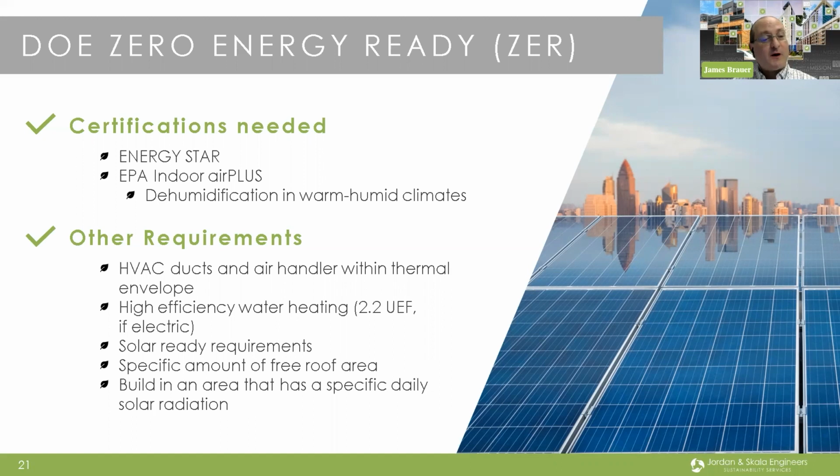Some of the other requirements outside of certifications is it does ask for you to have your HVAC ducts and air handler all within your thermal envelope. We touched upon earlier that have a high efficiency water heating system, which if electric, that does mean a 2.2 uniform energy factor, which translates to needing a heat pump water heater.